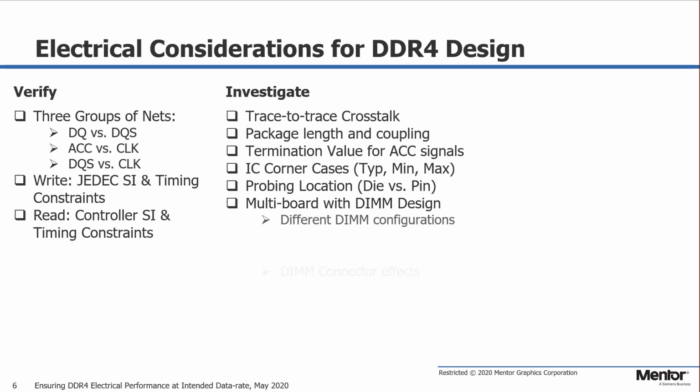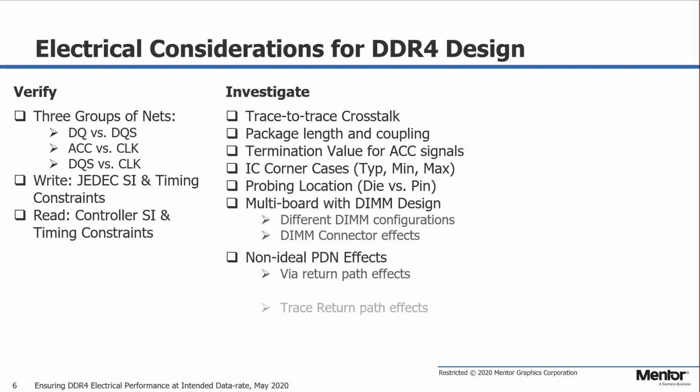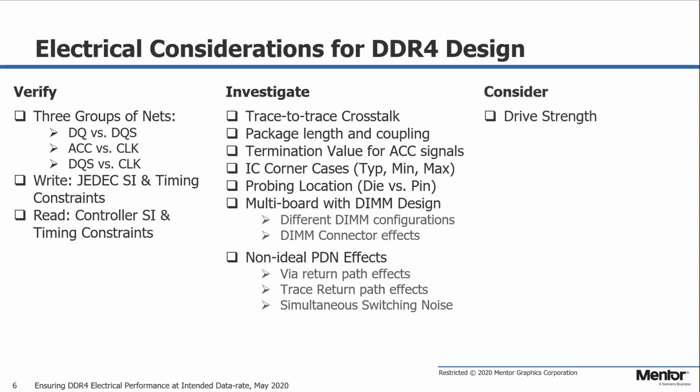Non-ideal PDN effects need to be investigated as well on how they affect the margins, but we'll cover these effects and simulations in a future webinar. In this webinar, we'll assume ideal PDN. You will also need to consider these device-related factors as shown in the third column in your post-layout analysis to maximize SI and timing margins.